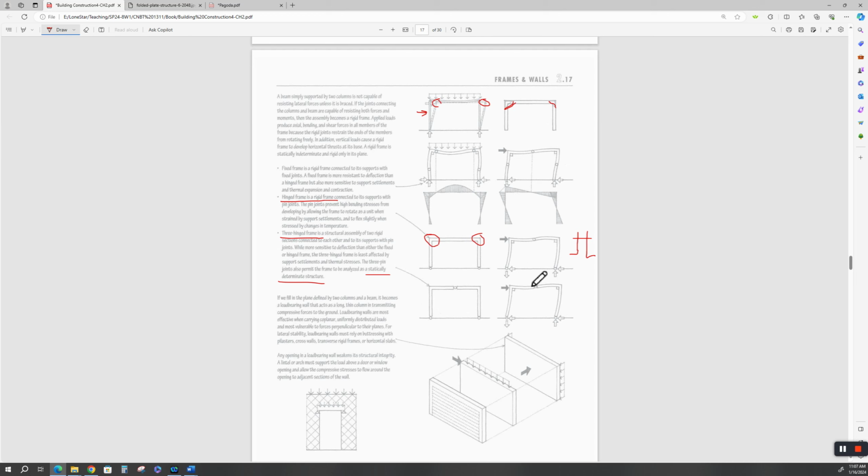See, so it's going to bend up here, but the bending is different because it gets to rotate around that point, and these beams can be a little smaller than if it was a total rigid structure. And if you'll notice, if you go look at a rigid structure building, you'll see that the gusset plates at these connections, they might be small down here, but the columns get bigger, and they have these bigger plates up here to connect to the upper structure, because all they're doing is just following these stress graphics. Okay? All right.